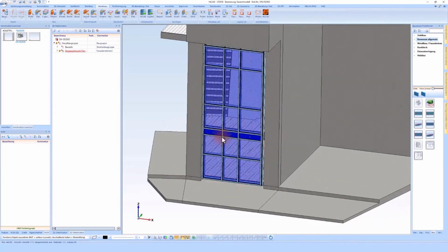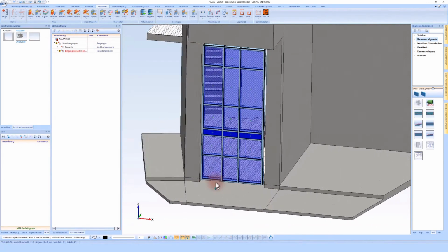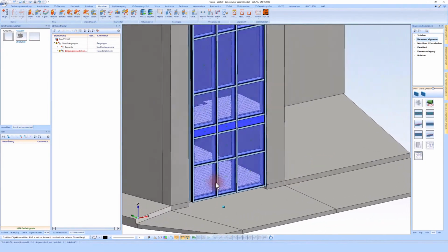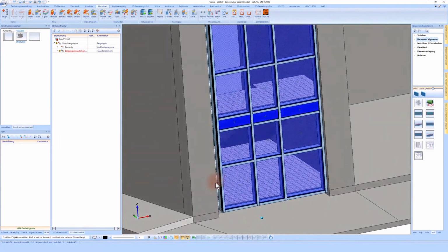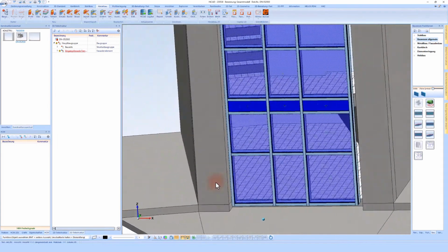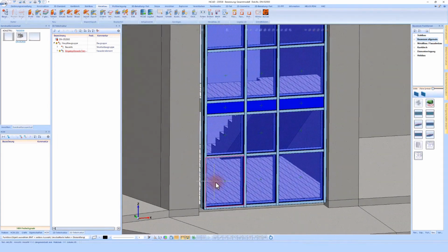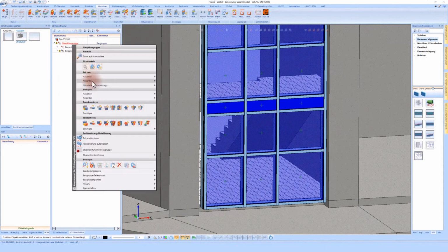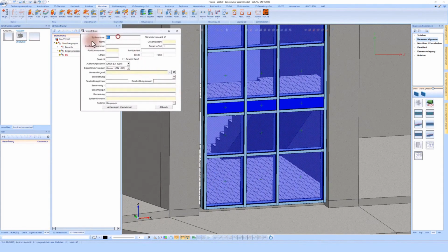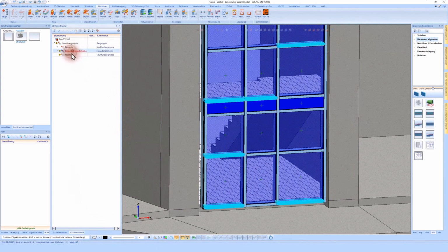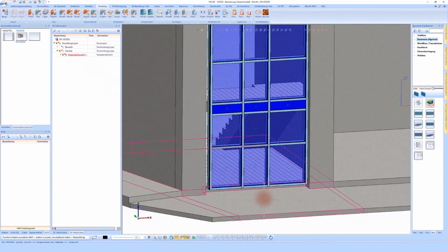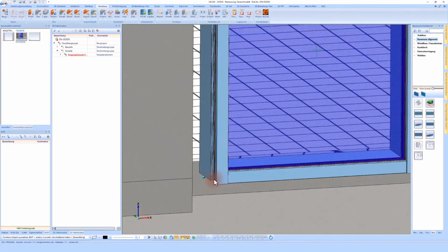And now you can see I have brought my facade from Logikal into HiCAD. This facade is, of course, linked with Logikal, which means I can continue to edit it at all points. In the first step, I want to create a new structural assembly for the facade, where all my facade parts are included, because I will need this for my detailed drawings and further evaluations. So, I will save the construction for now, and then we will move on to the next steps.